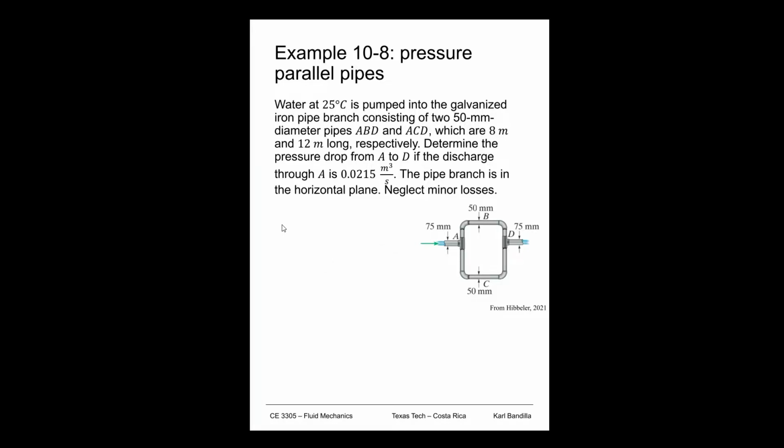So let's maybe start out by just finding the relationship between the two velocities, and of course that will turn to continuity. Right, we know of course that the water that's coming in at QA has to be the same as the water that's flowing out, QD. And maybe we'll just call that Q, right?